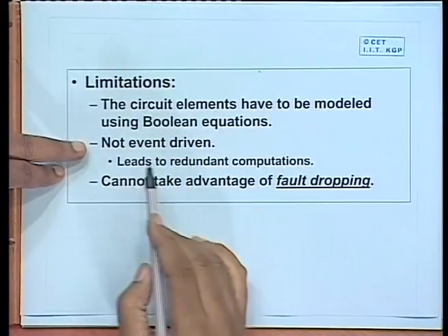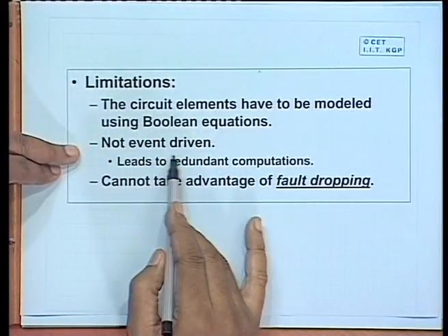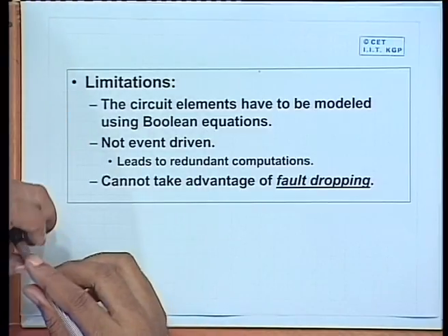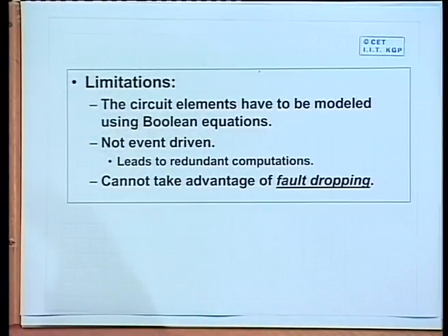And second thing is that it is not event driven. Event driven means sometimes in order to speed up the simulation process, suppose we apply one input to the circuit, we simulate to evaluate the output. Now, we apply the next input. After applying the next input, we find that only in a small portion of the circuit there are some changes in the logic values.